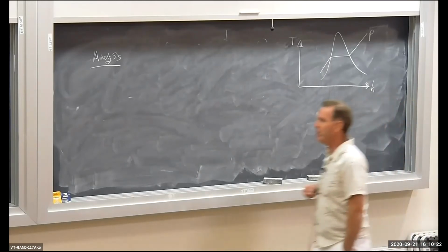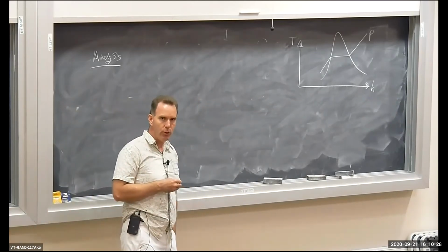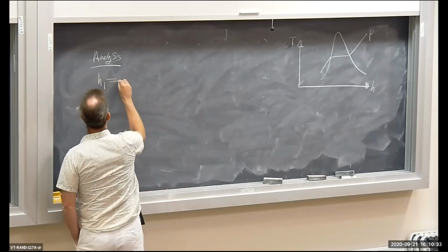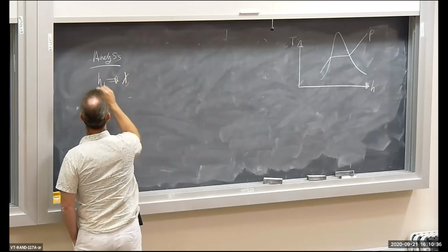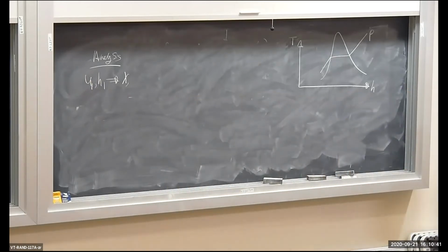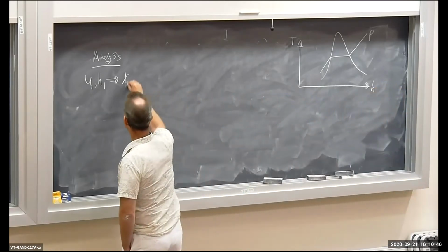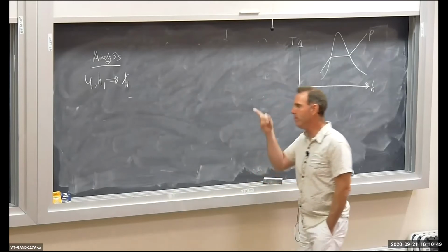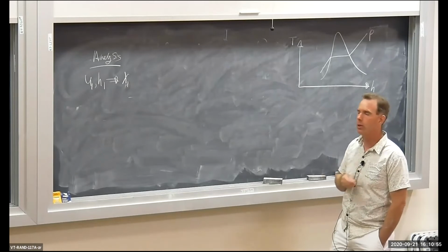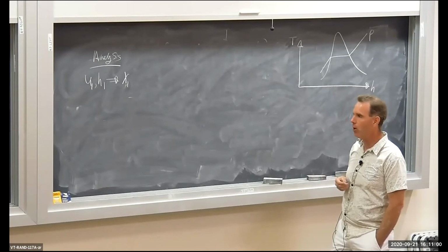So I want to know what the inlet quality is. Now, if I had an inlet enthalpy or an internal energy, if I had H1, I could get a quality at state 1. Or if I had a U1, a specific internal energy or a specific enthalpy at the inlet, I could get the quality at state 1. So really, the problem should be driven by trying to find the inlet specific enthalpy, H1, or internal energy, U1. So what equations have H's or U's in them as far as open systems?